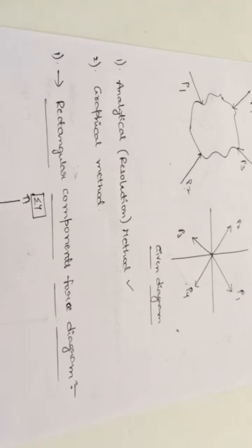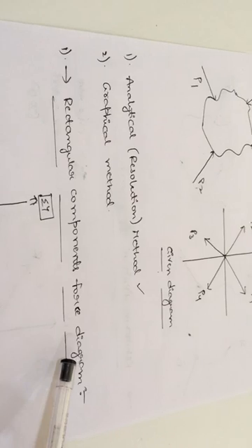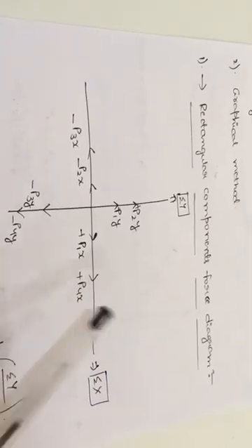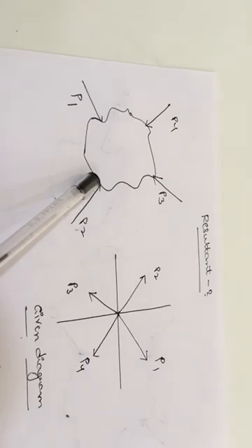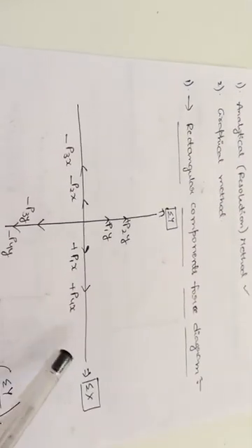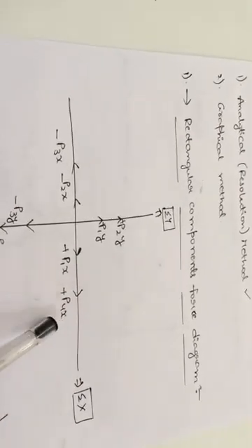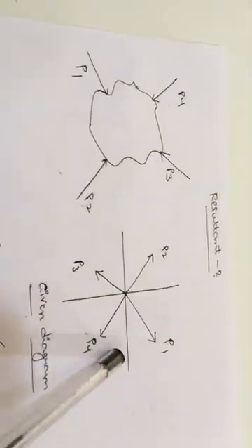Before going into the resolution method procedure, first of all we should know about the rectangular components force diagram. If we draw the diagram which consists of only the x components and y components of all the forces acting on one particular body, that diagram is nothing but a rectangular components force diagram. Once again, the diagram which consists of all the x components and y components of all the forces acting on a body is the rectangular components force diagram.